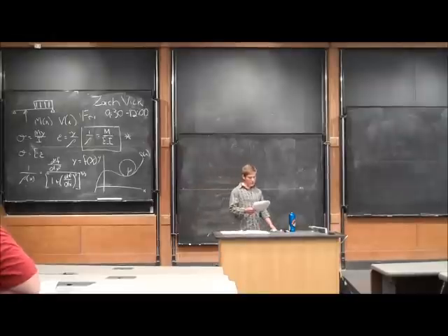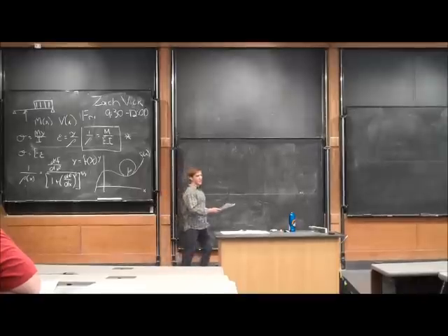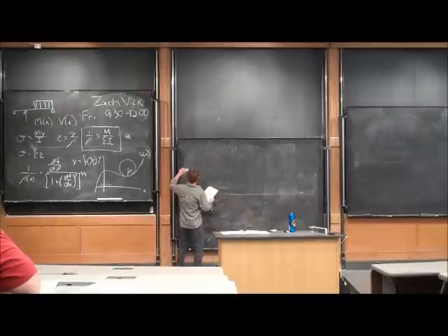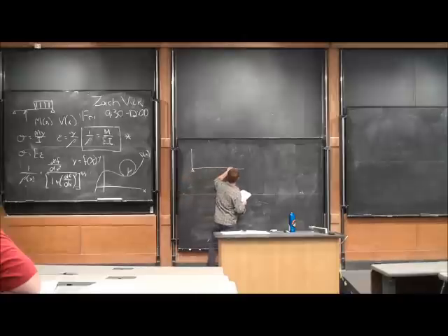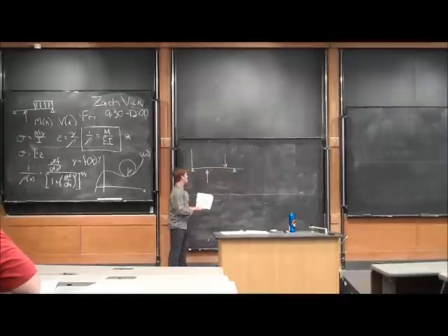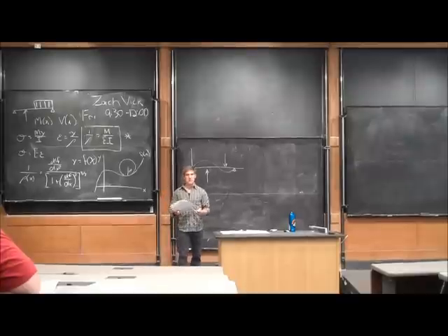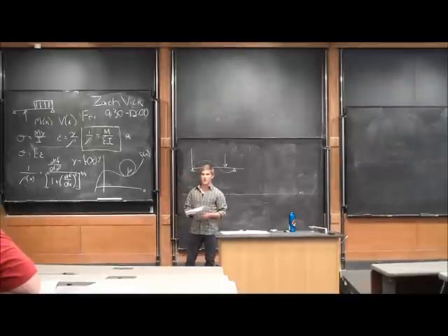So, if we're looking at a beam, and we're loading a beam in a particular manner, that beam is going to deflect, right? That beam is going to bend. So if I get another color, it'll probably help out. If we have some coordinate axis, and we have some beam that's supported on that coordinate axis, if we apply loading to that beam, it's not going to continue to stay straight. It'll actually deflect due to that loading, right? So we want to be able to predict how much a beam can deflect, because that's an important thing to be able to do if you're looking at structures.